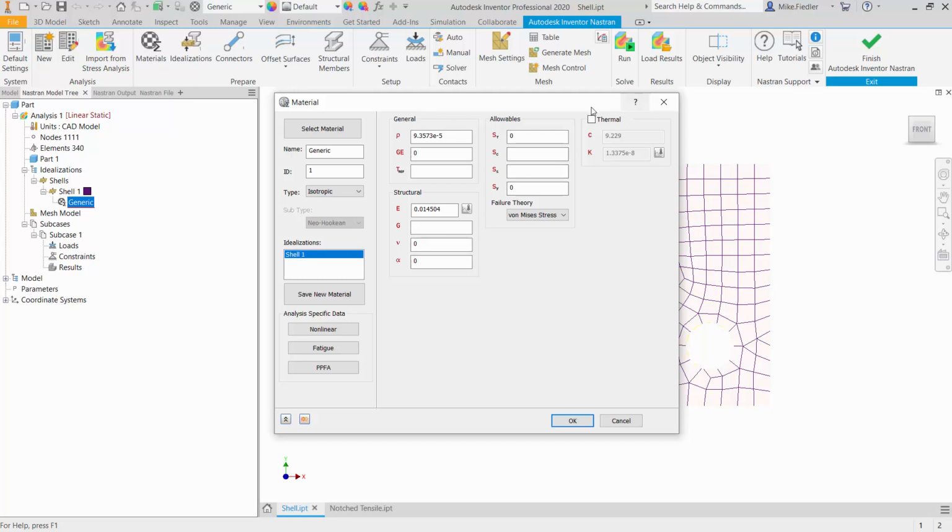And then if you're going to include some thermal effects, you probably want to identify a reference temperature and activate your thermal properties so that you can define the specific heat and thermal conductivity. So this is all fine and well. Your isotropic, elastic material properties are perhaps the simplest and most straightforward ones. And there are a lot of videos and tutorials which cover this material model, so I'm not going to spend a lot of time here.